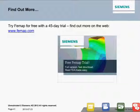This one appears to come from a current FEMAP user. They wanted to know what output settings they need to use to have results not import and attach. What you're going to want to do is go to File, Preferences, go to the New Results tab in FEMAP 11 or 11.0.1, and there's an option in there to automatically attach results when you import results. Okay?